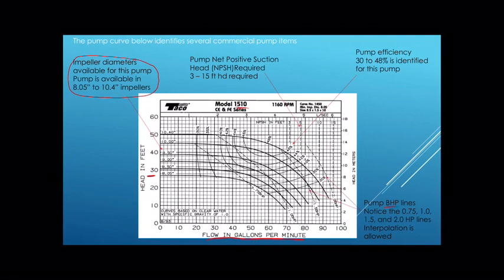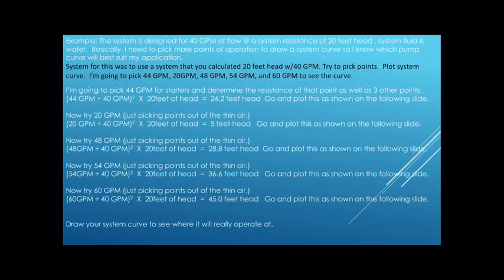And oftentimes they will note that or stamp it or mark it so they know what's in that pump. Otherwise, you really don't know. You can also tell that the efficiency range of my pump is much better in that middle third to some extent. So if we wipe this out and we wipe this out, you'll notice the middle third is really my sweet spot on there.